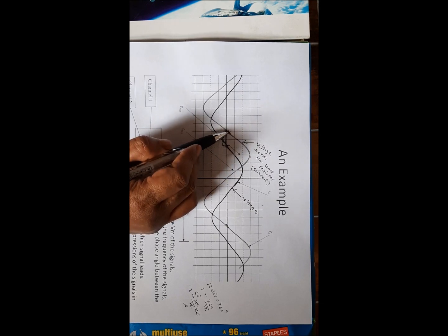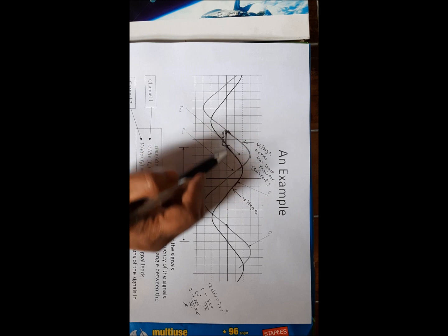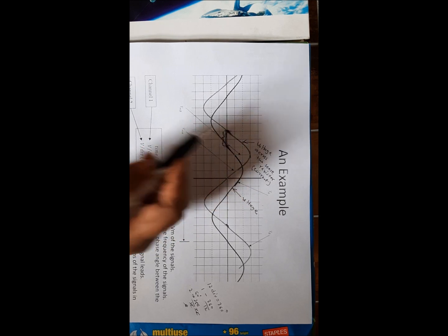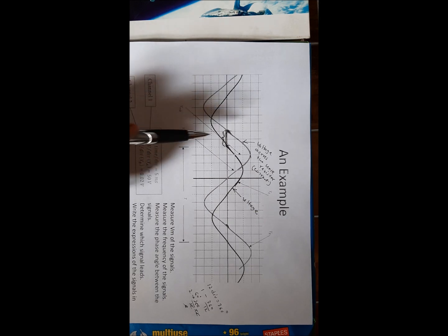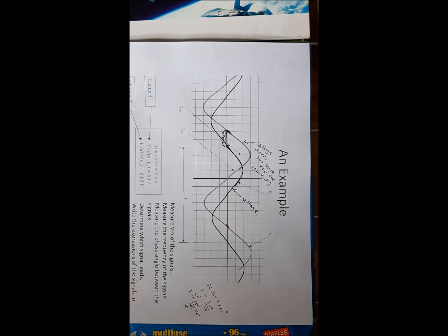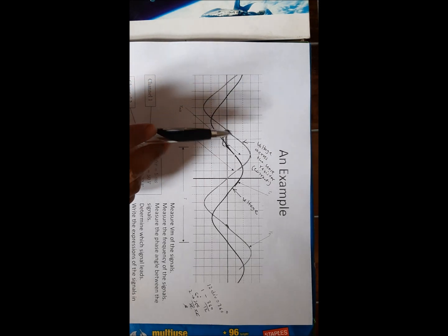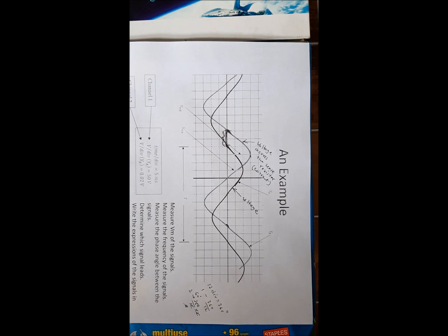So as you see the current is leading, so it must be an RC circuit, because in an RC circuit the current is always leading the voltage. And if it is the opposite, that means voltage leads current, that will be an RL circuit. So by observing the signal on the oscilloscope screen, you can easily determine whether your circuit is an RC, capacitive circuit, or an inductive circuit. For a capacitive circuit, the current will lead, and for an inductive circuit, the voltage will lead. So it is very easy to find this.